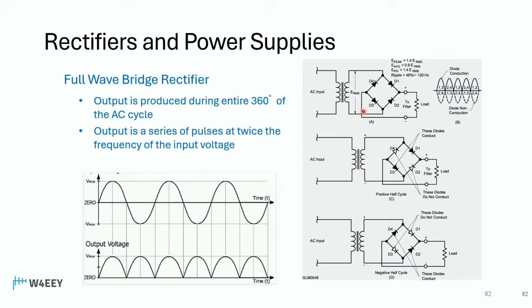And what we're doing here, the magic is that 2 diodes will conduct, and this kind of explains it here. Kastler went through this as well. But on 1/2 of the cycle, we get one output. On the other half of the cycle, we're conducting through the other pair of diodes, and we get another output. We wind up with something that looks like this. So we have filled in those humps in between what we saw in the half-wave rectifier.